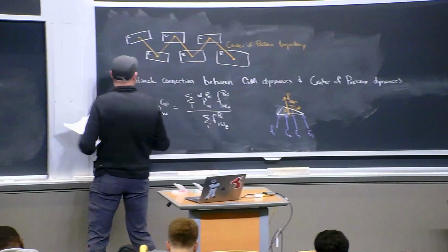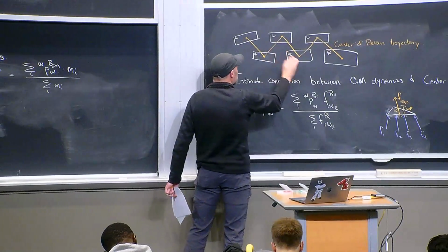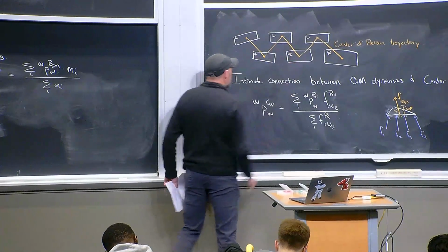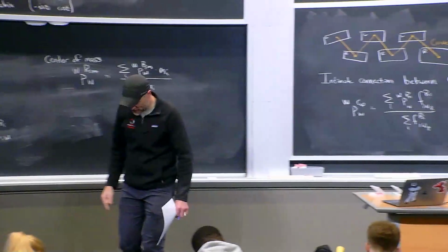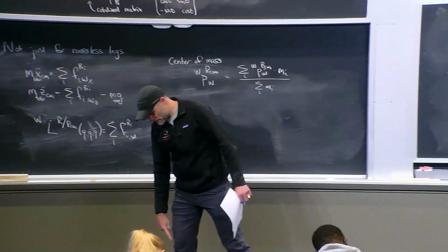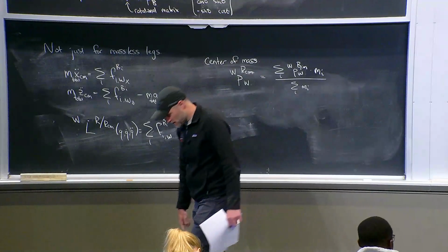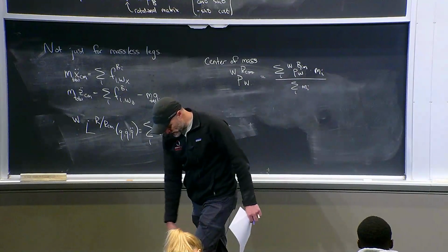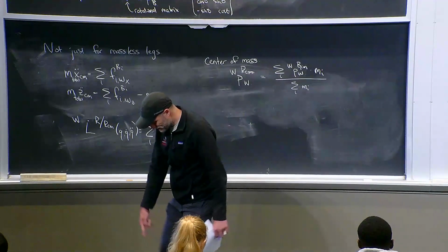Okay, we need a schedule of our feet over time, and we're going to need a schedule of this over time. But roughly speaking, I'm going to plan that at some moment, my center of pressure will be exactly in the middle of this foot. When that happens, I'm going to lift this foot over. Okay, I'm going to put it here. I'm going to move in a straight line between the other foot. I'm going to move it there.